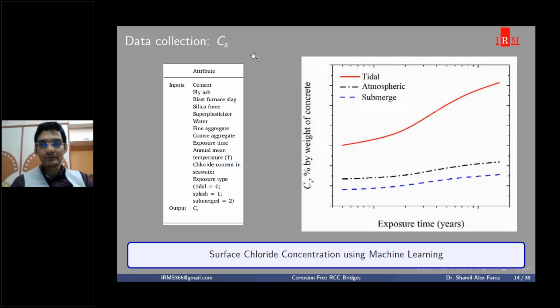Just like whenever you are designing your bridge or viaduct for an axle load of a train, like 28 ton, that is a load which is coming on your viaduct. Similarly, for this deterioration load or chloride load, we need to quantify the amount of chlorides that are attacking your structure. That can be identified in various formats, and one of the formats I am showing here.